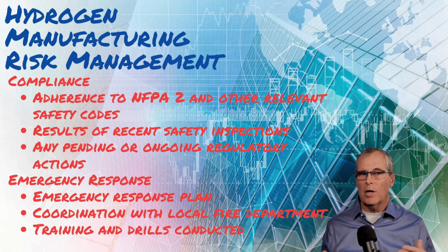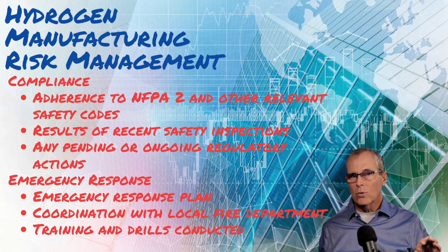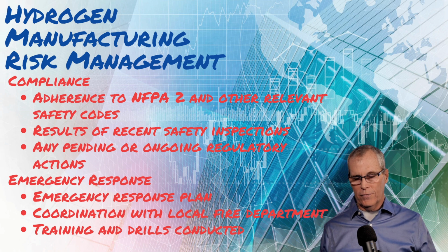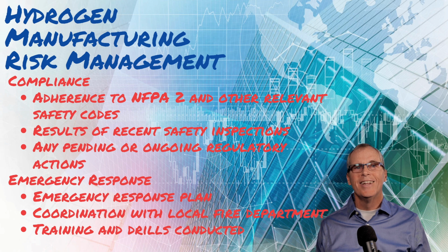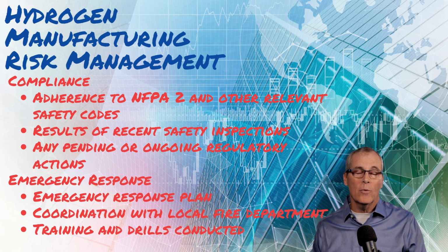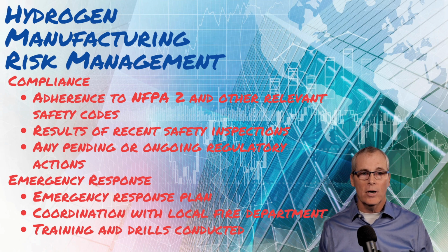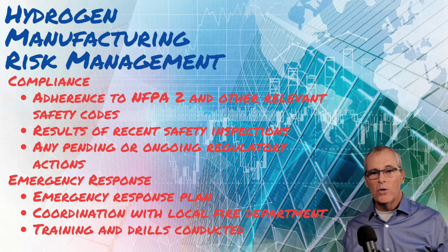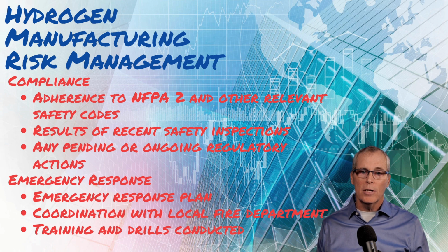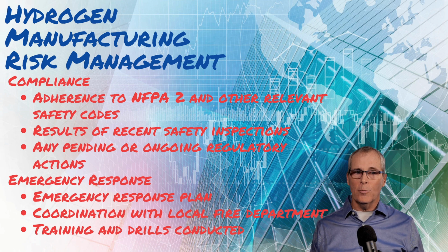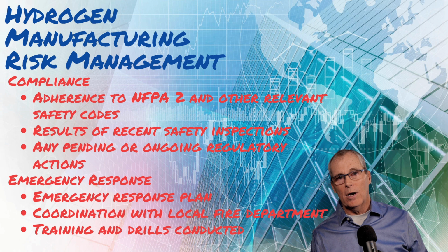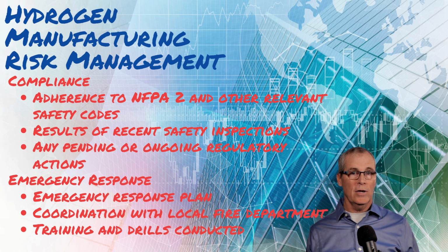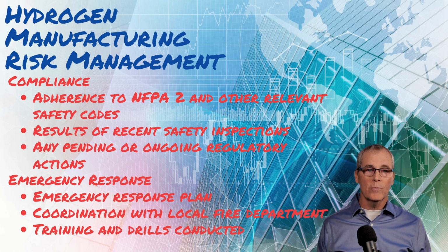We're going to look at, do they comply with NFPA 2? So you do want to point out if there's any large discrepancies between what their operations are and any of the current codes and standards. However, your review is not a code review, and anybody who reads your report should not think that because you didn't mention anything about NFPA 2 that they're in compliance with NFPA 2. Couldn't be further from the truth.